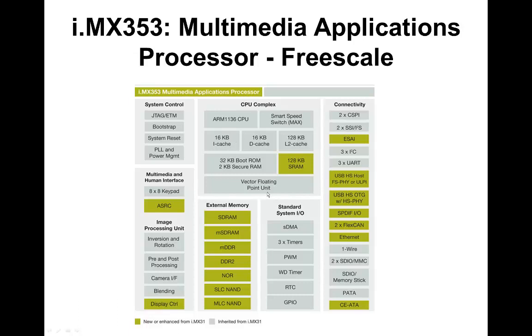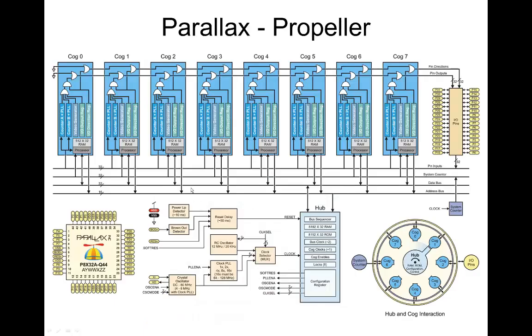And then again, we see some other things here like PWM, real-time clocks, GPIO, timers that are pretty standard type things. We saw a lot of connectivity things, let's say I2C and UART. But there are other different things like the CAN driver here. A CAN is usually for automotive or maybe aircraft type things. It's a serial protocol with extra reliability built in. Don't want to crash your plane. Then we have memory controllers for different types of memory, like DDR memory, image processing type stuff, and then some system control and boot up.